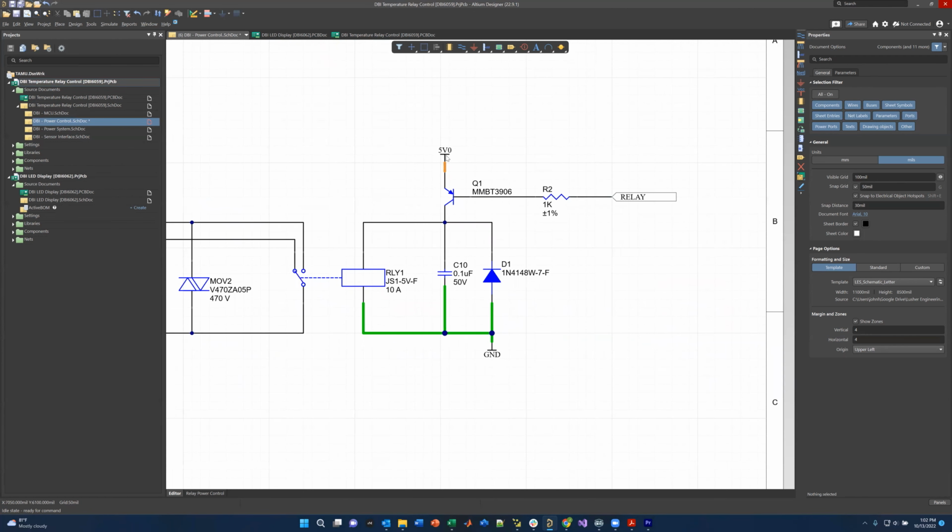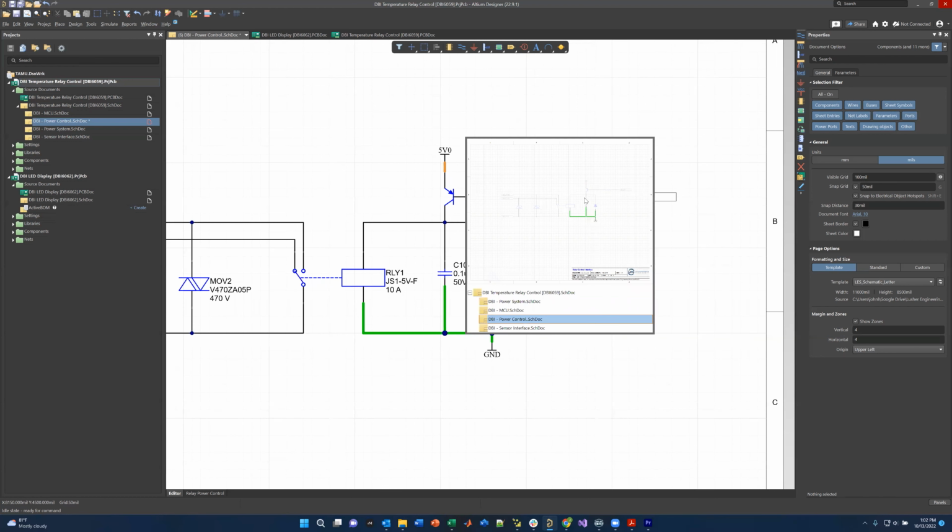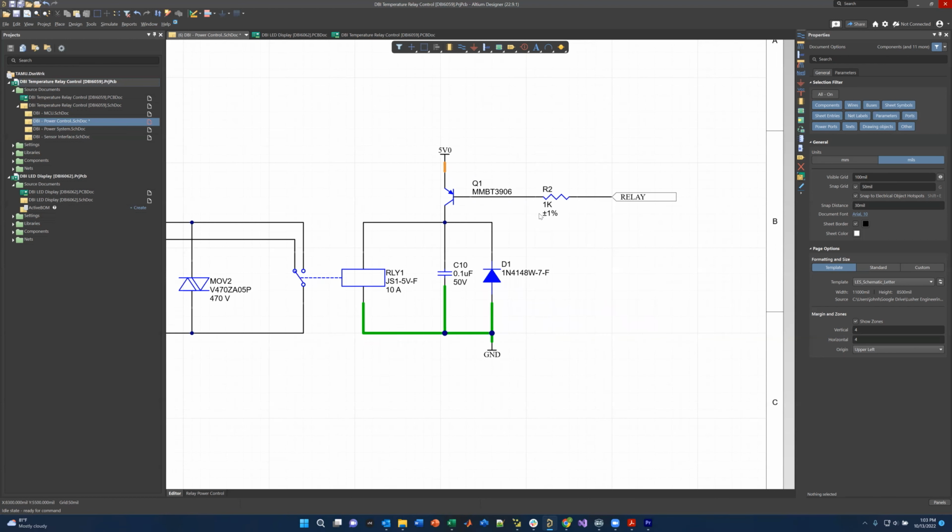Over here, we've got 5 volts coming in onto a transistor, and this transistor is being driven from the microcontroller directly. We push current into, or basically current is being pulled. So this is 0, this transistor activates, current flows, goes through the relay, and the relay turns on. If there's a high signal on this pin, or it's just open, no current flows, the transistor is off, the relay is off. These two I've covered before in other lectures.